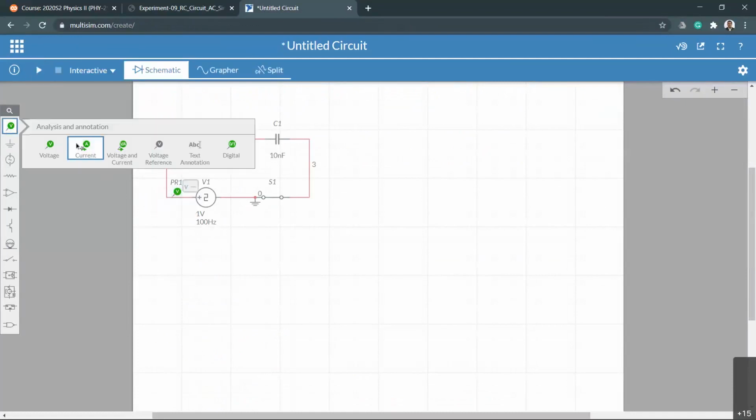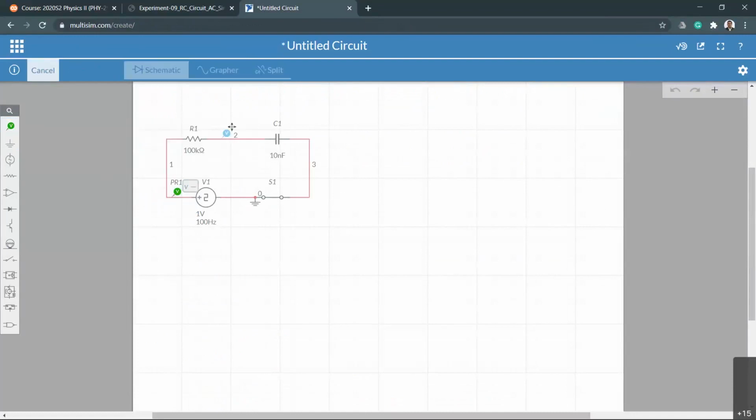And for the voltage across the capacitor, I need another sensor just before the capacitor, on the positive side relative to the positive side of the input voltage. Okay, that's important, otherwise you will not get the right curves. Now we have the circuit and the sensors, everything is fine. All you have to do is simulate this. Click the run simulation icon, then you can see it simulating.